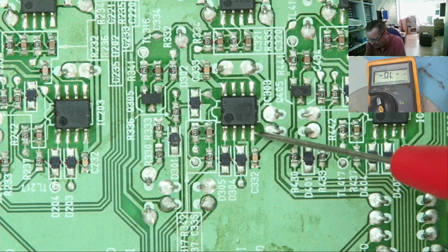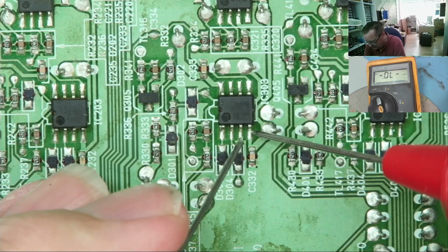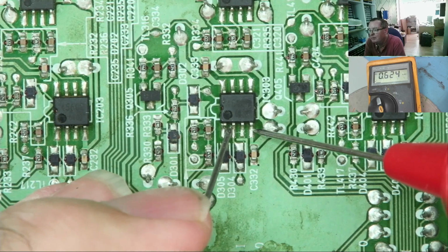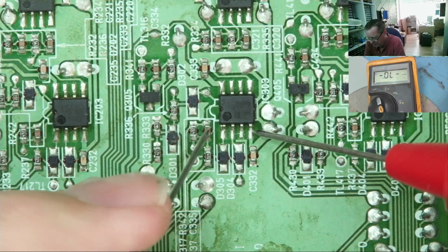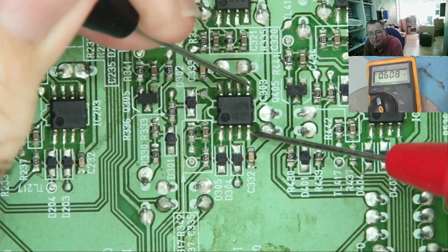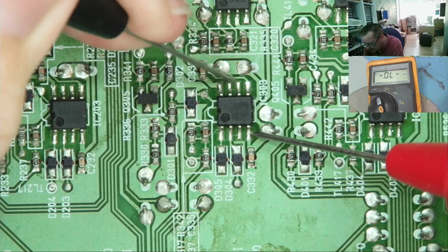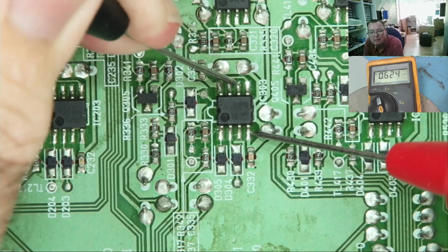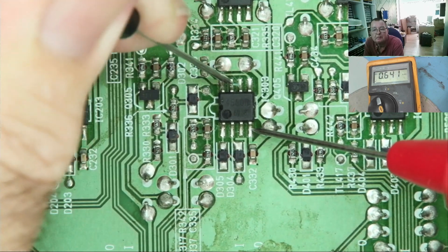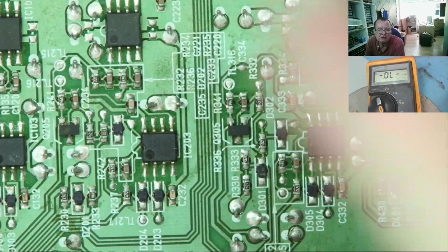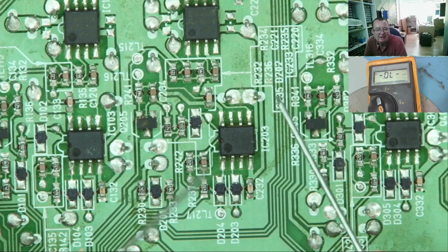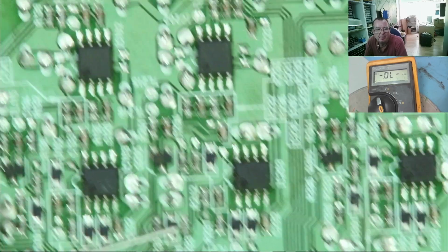We've got a third one. And if these are reading like this, almost certainly there's no severe problem. Again, that one reads a bit lower. 624. Down to it. 640. 608. 624. 642. So they read like each other. If you find that, it's extremely likely they're all okay. That's a quick and dirty way to test op amps.